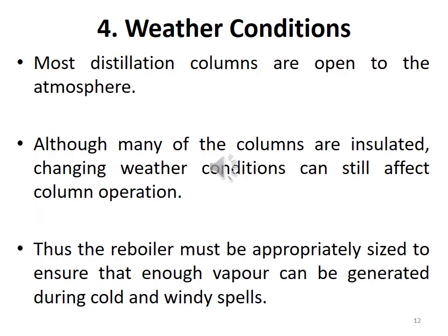Weather conditioning is the last parameter which affects the efficiency of the separation in a distillation column. Most distillation columns are open to the weather conditions. However, many of the columns are insulated, but the changing weather conditions can still affect the column operations. Therefore, the reboiler must be suitably sized to ensure that enough vapors can be generated during the cold and the hot season.